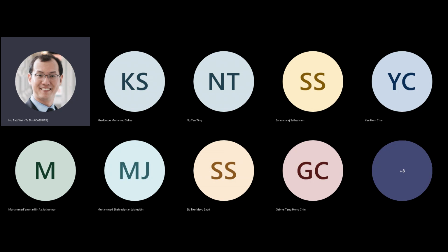This is why all transistors have a temperature limit at which you can operate them. Room temperature, as well as sometimes you come across what's called the junction temperature. The junction temperature is literally the temperature at the edge, the boundary of the PN junction of the device. So that temperature heating effect can come from the environment. It can also come from the local heating due to the current that's flowing in this. So that's the temperature effect.